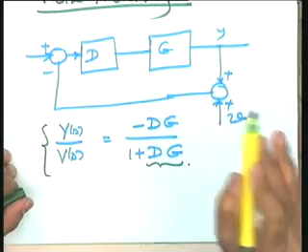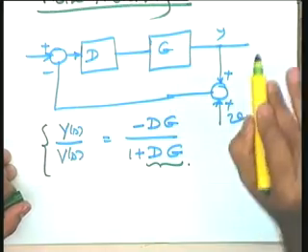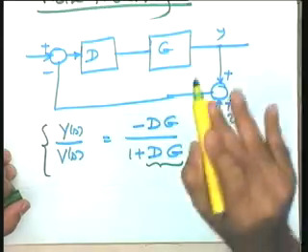You will have to study the environment in which your sensor has been installed, the effect of the environment on the sensor, and what type of frequencies will enter through the sensor has to be studied, and then a suitable high frequency filter should be designed so that the high frequency signals are not allowed to enter into the loop, and hence this will not come in your way as far as taking high loop gains is concerned. Okay.